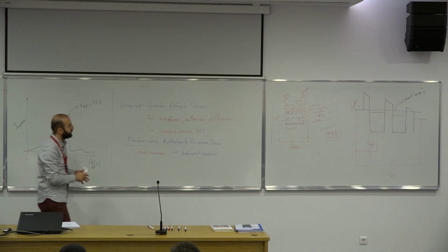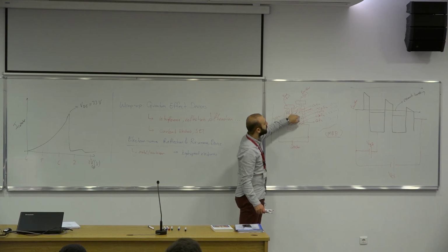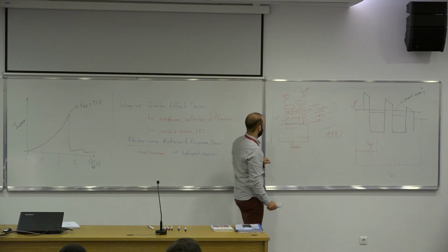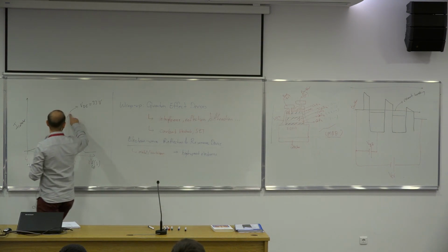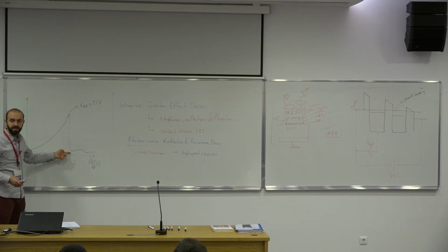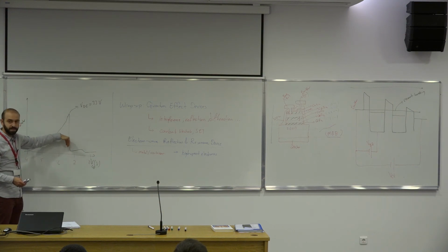The interference between the tunneling of electrons through these layers is enhanced by the increasing voltage till a point where you no longer satisfy that resonant tunneling condition. So the resistance increases, although you increase the voltage even further. So we're talking about a negative differential resistance. Although you increase the voltage of the device, the current that you get decreases.